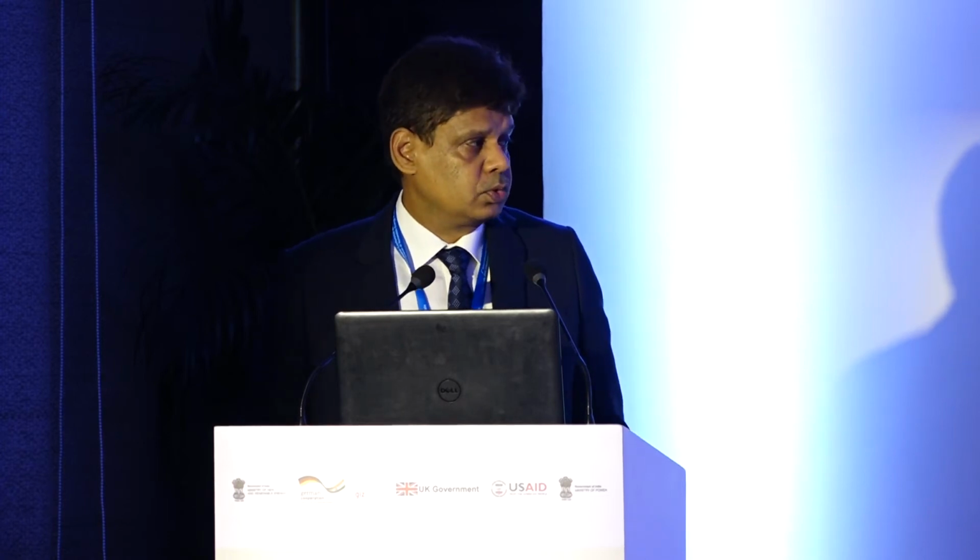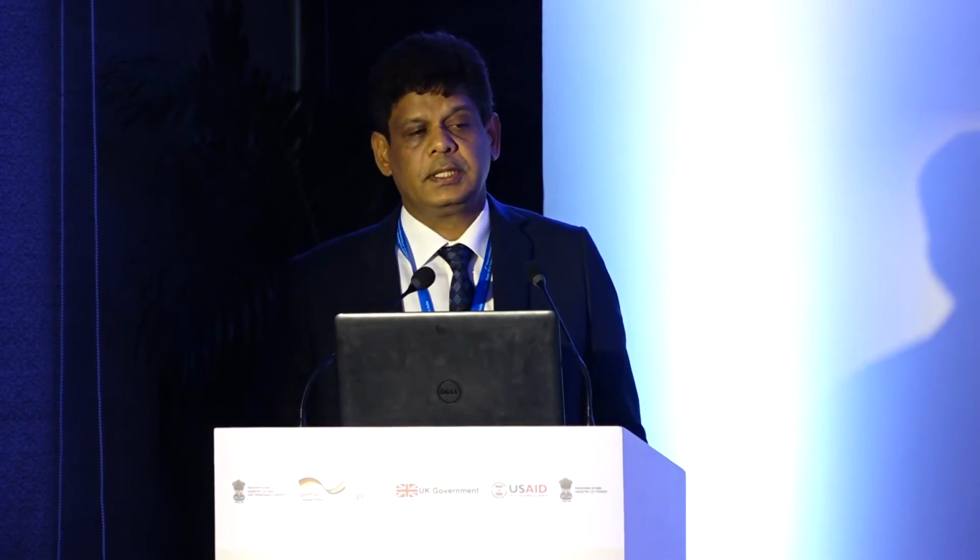So there are 5 or 6 key steps to reach a good level of accuracy, because here accuracy levels of less than 98% are not acceptable to the SLDCs or to the RLDCs, whosoever is taking the forecast. And when we say 98%, it's not an average of 98%, but the expectation is that you achieve a high accuracy in each of the 96 blocks.